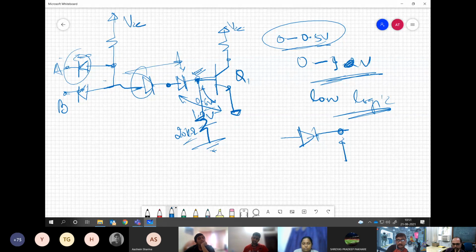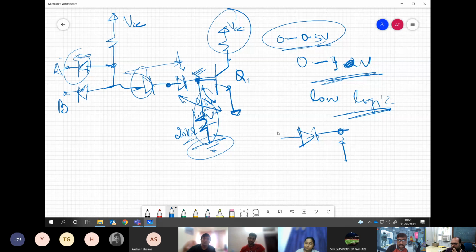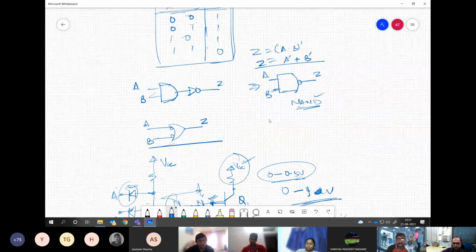So that is what we do. We connect a high impedance to ensure that whenever any reasonable voltage is not here, it is dictated by this ground. So we may have this pull up or pull down, these kind of configurations, to ensure that if anything significant is not there, it is defined in this state. That is why you will hear the names like pull up or pull down. Clear? Yes, sir.